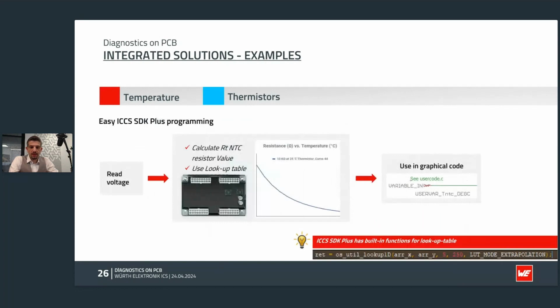One other challenge with those NTC is that the response impedance to temperature is not linear. Therewith, we need to calculate such conversion within our programming, allowing us to directly offer a temperature in Celsius degrees to our system.